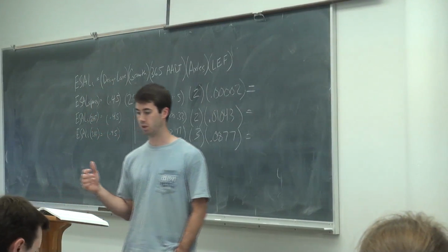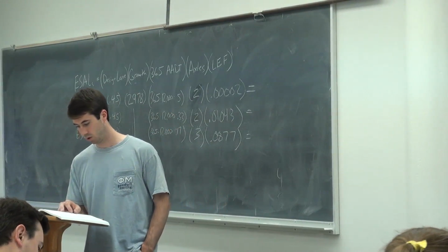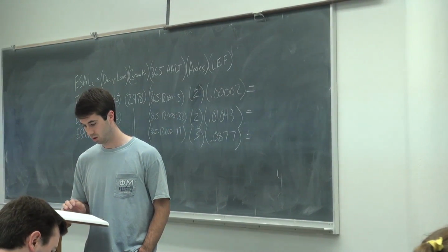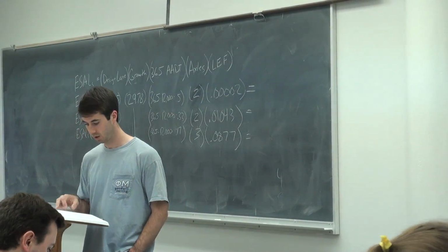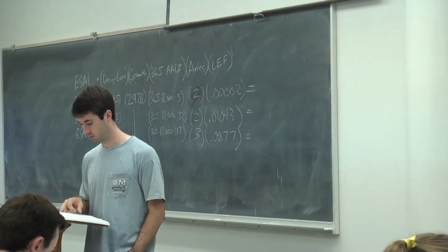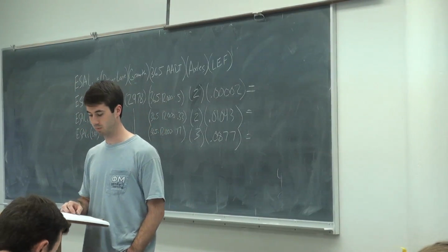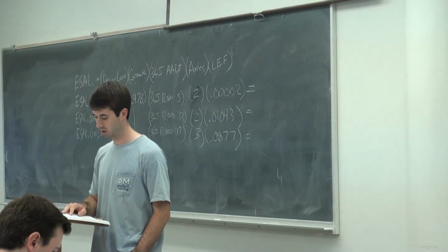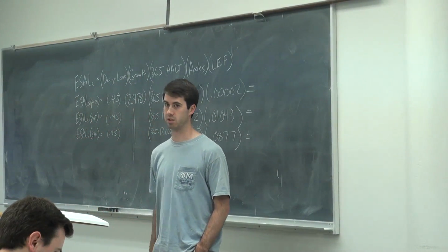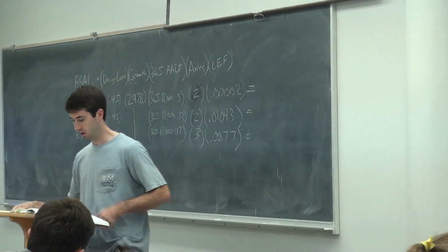What page is that? 134. So to calculate those two equations, you need D10, D30, D60. Those I got defined here. Basically just whatever grain size has 10% finer or 30% finer or 60% finer.